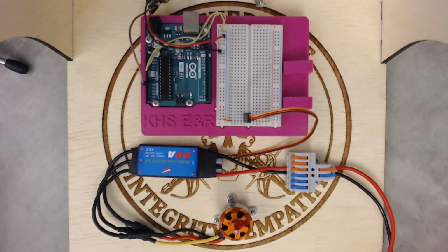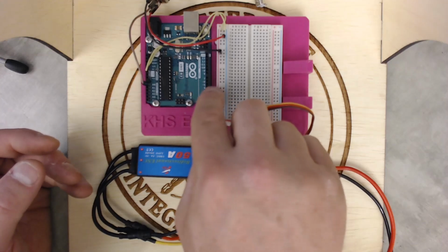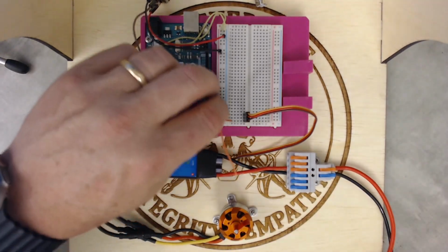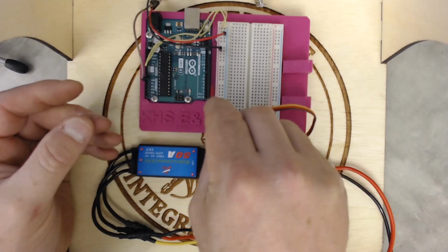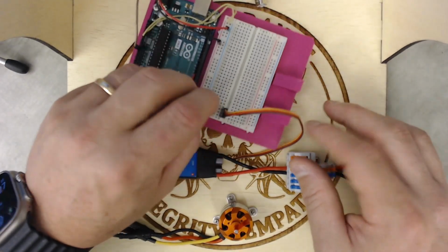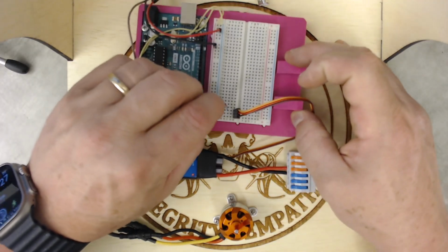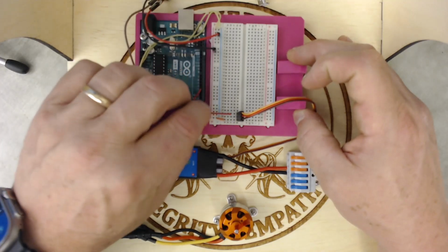All right. Now the next thing we need to plug in is this yellow wire. This yellow wire is a signal wire. This is where the Arduino is going to be sending the speed signal to the ESC. And for this we're going to use pin 3. We could use any of the tilde pins for this purpose, and this wire is going to be way too long. Let's see, I'm going to get a red one. So I'm going to go from pin 3 on the Arduino, bend it straight over, and then go to the outside pin, the yellow pin on the ESC cable. And again, anywhere inside there is totally fine.